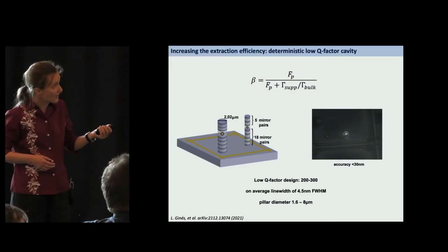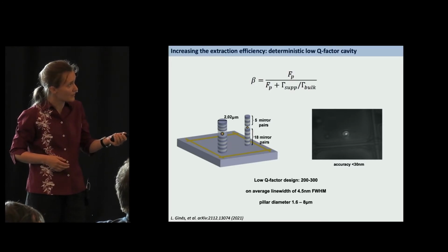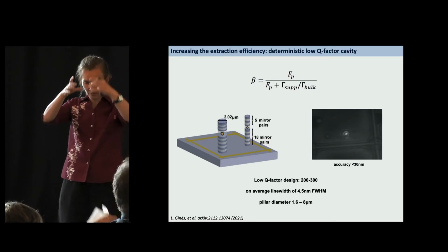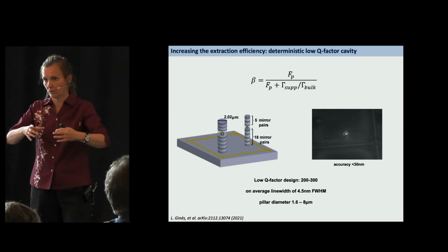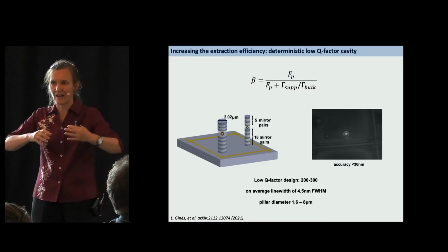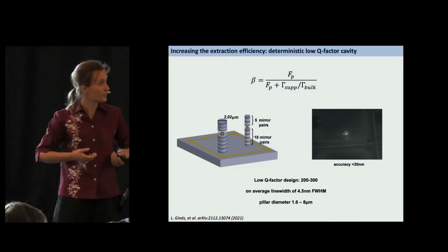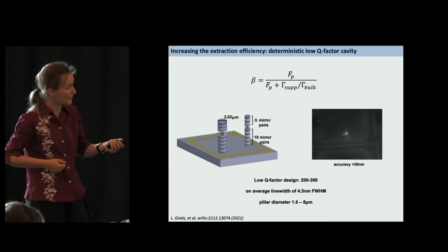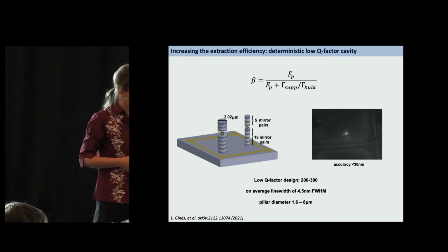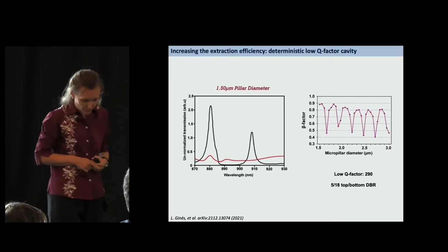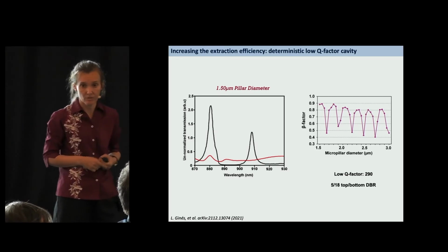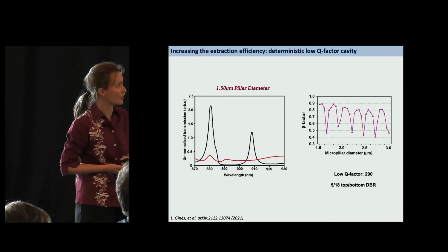So what I have to tell you is that these micropillars were placed using hyperspectral imaging, which means that they were fabricated at the site of formation of a quantum dot. But since we already start with a microcavity before the fabrication, we have excellent signal for the alignment. So the precision with which these micropillars can be placed is something less than 30 nanometers. So in the simulation, we discovered that the beta factor can still be big. And the reason for that is this suppression of the modes that are not resonant to the cavity.